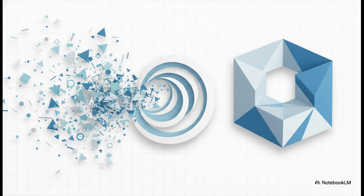To fix this, FLAT applies a very quick, lightweight refinement step. Over just a few optimization iterations, this process snaps those disconnected vertices right together. It forces the transparency to become completely opaque, and it sweeps away any floating junk. In literally seconds, that loose triangle soup is converted into a fully solid, impenetrable, game engine-ready mesh. No more hollow mist, just solid, explorable architecture.